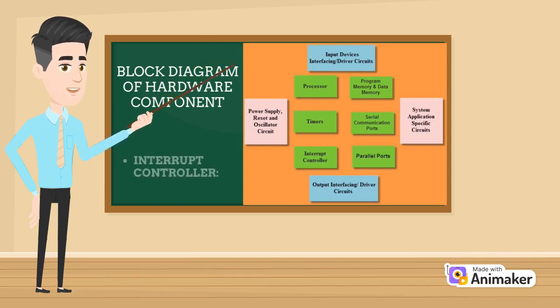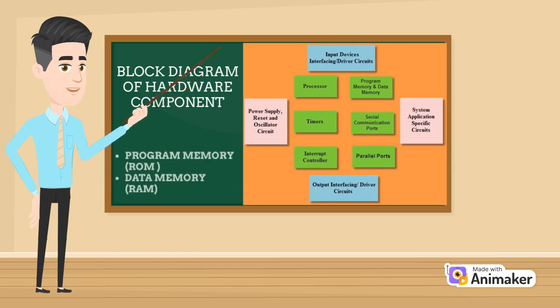5. Interrupt controllers. It multiplexes a number of possible interrupt sources on the platform for presentation to the processor. The interrupt controller in the embedded system must be configured to prioritize and route interrupts from devices within the SoC, system on a chip, and externally attached devices. 6. Program memory, ROM, and data memory, RAM. Program memory, ROM, is used for permanent saving of the program being executed, while data memory, RAM, is used for temporarily storing and keeping intermediate results and variables.